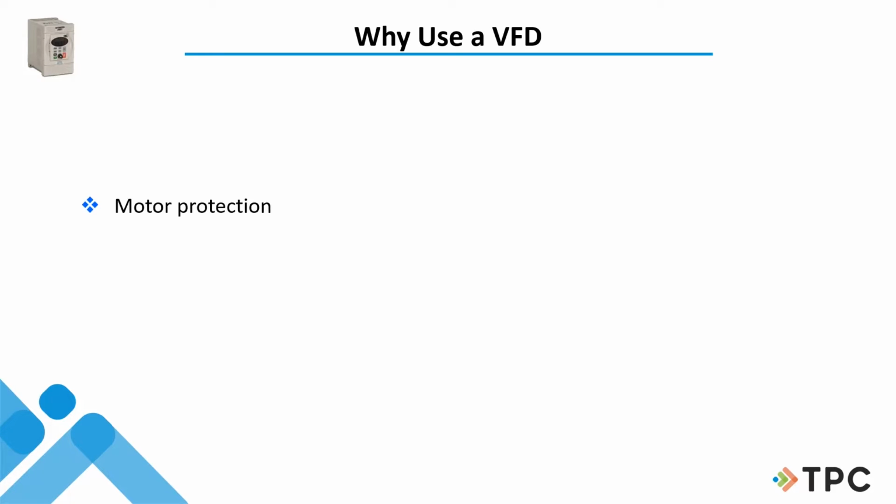Motor protection. Well, with across the line motor starters, we have our overload block, our heaters we've had for years and years and years. And they work, but they don't work as well as the ones in a VFD. And I get to program that into my VFD. And the other thing I can do is a VFD can have torque limiting. So with typical motors, the motor has to go over amperage to create the heat on the heaters to get it to finally trip out.